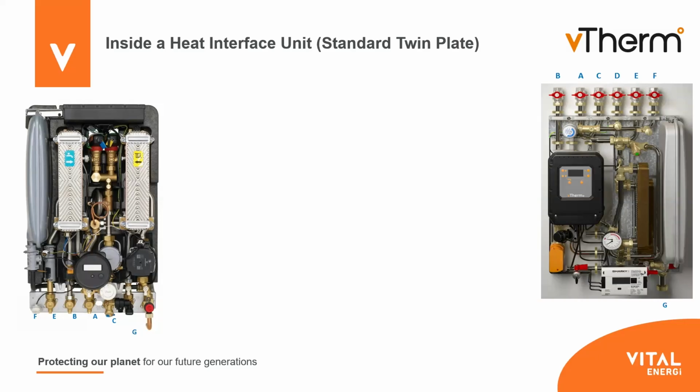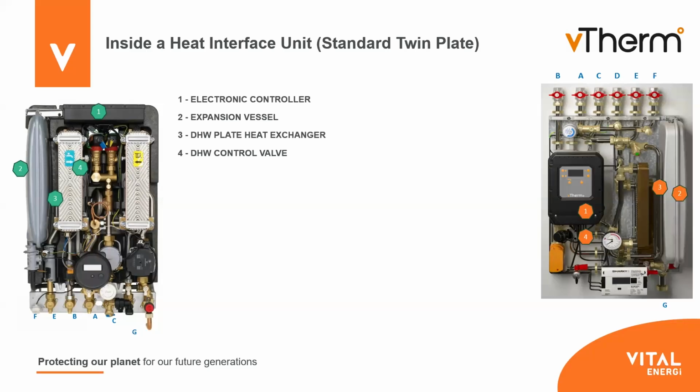Retrofit, as I say, you could have a bracket. If somebody's already had pipework, we get asked to make our brackets taller in some cases to help with retrofit projects. But let's talk about the actual components. So first of all, you can have some form of electronic controller. Some have displays, some don't. We'll then talk about the expansion vessel, therefore on your heating circuit. You'll have your plate heat exchanger and of course some form of control valve to actually control that.